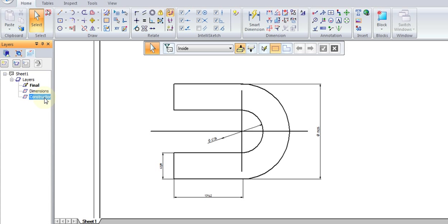Because there are times, as you'll see in your first tutorial, that you may need to use construction geometry to make reference points and reference lines so as to create the rest of your geometry. Now in reality, we don't really want to see construction or construction lines in our final drawing. And depending on how many dimensions we use and where we place them, a drawing can become cluttered if there are too many dimensions. So we want the option to actually be able to view the drawing without dimensions cluttering our view. So let's look at each of these layers and see what we can do in terms of cleaning up our view here. So as I was saying, you don't really want to see construction geometry.